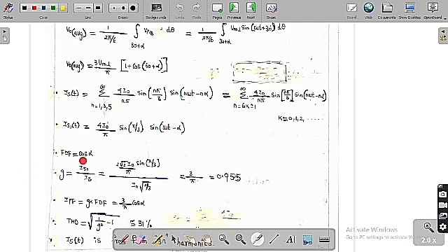So the fundamental displacement factor is equal to cos alpha, whereas the distortion factor is equal to the RMS value of the fundamental source current divided by the overall source current. To find the RMS value of the fundamental, we divide by root 2. So if we divide 4 I naught by pi sine of pi by 3 by root 2, we get 2 into root 2 I naught by pi into sine of pi by 3. So we get this expression.